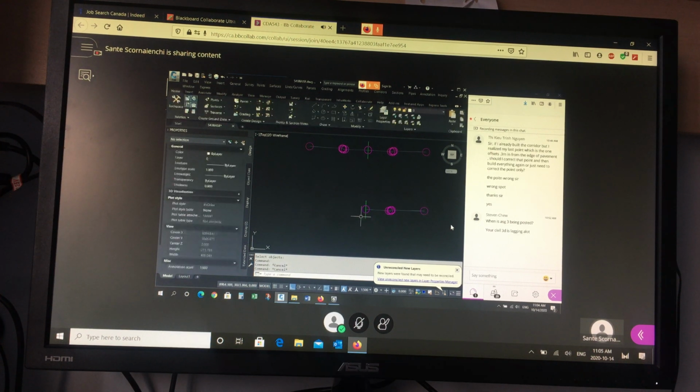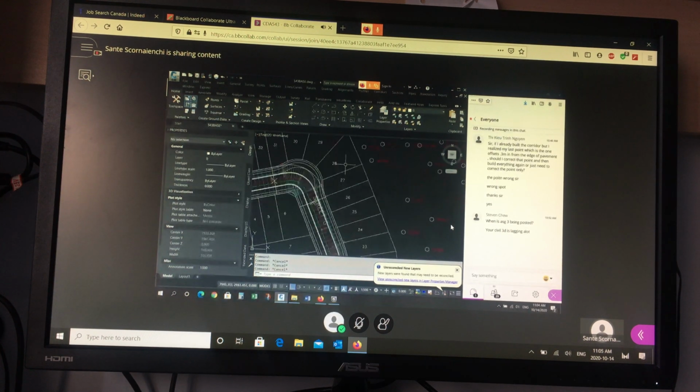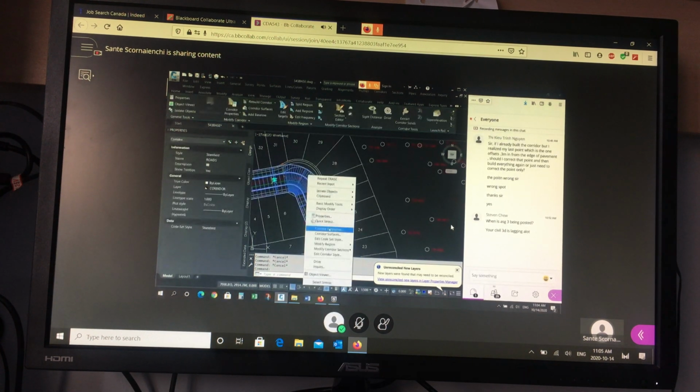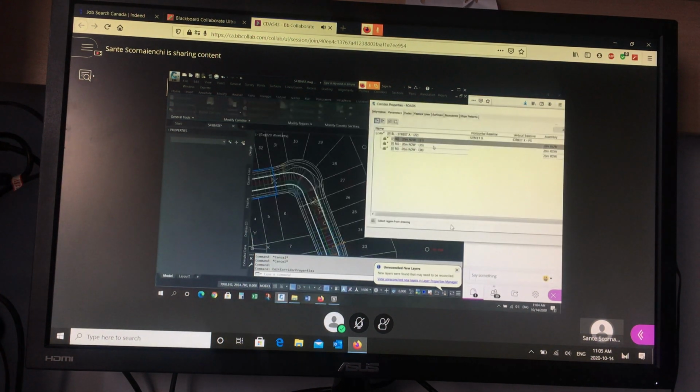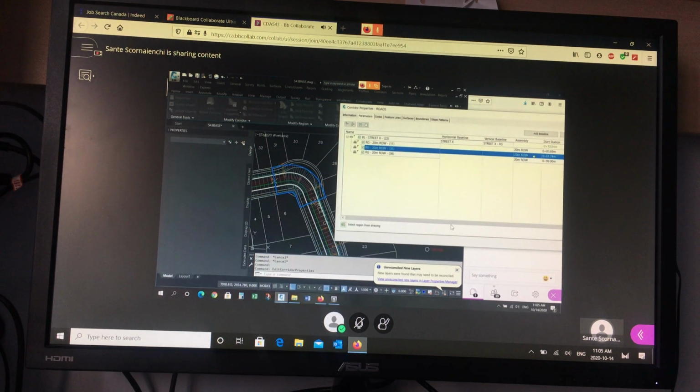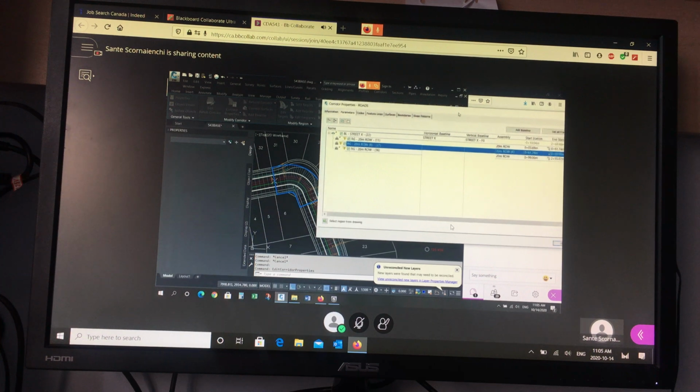So now what I want to do is I'm going to go to the corridor and replace this cross-section with this cross-section. So this is the first step. I'm going to go to this corridor, right-click, go to Properties, and then I'm going to go to that region in the middle, and I'm going to swap out the right-of-way. Not the full 20, but the 20 right side only. And when I say OK, watch what happens. It's going to want to rebuild, so I'll say OK.